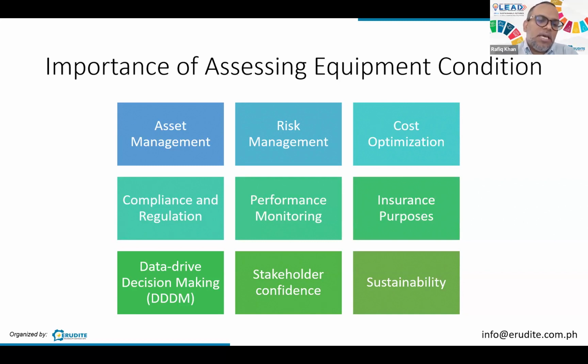Compliance and regulations: DOSH, the Department of Safety and Health, for example, may require a condition assessment before restarting a power plant. When you have a major overhaul, before restarting a power plant, in Malaysia at least, it's a requirement that you do a condition assessment. So power plant owners need to run this kind of assessment before they are able to get a permit to restart their plants.